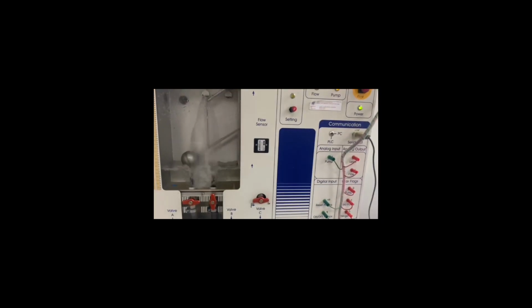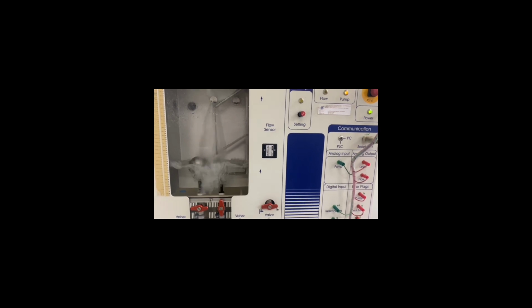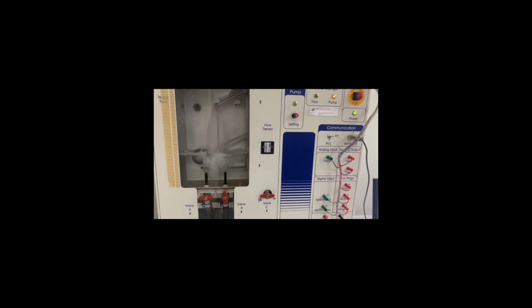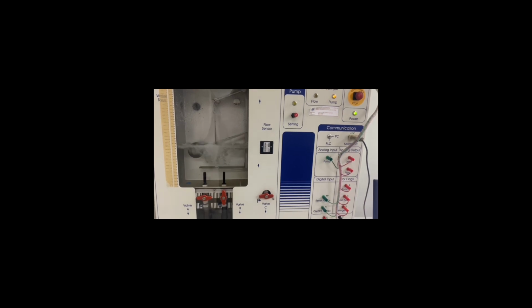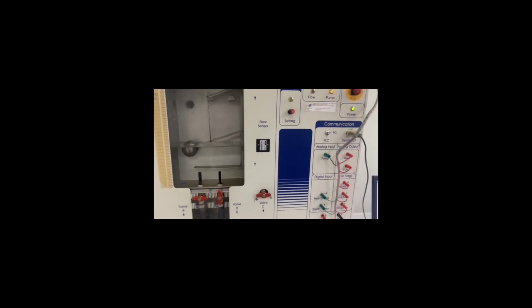I will continue the experiment video, and I will talk about the procedure for this experiment. The first step is to turn on the computer and run the Process Motion software. For the first task, at the screen, click online, click the level control or process button, and select the PID controller from the dialog box and enter the input for set point 120, KC 5, TI 100,000, TD 0, and MO 0. And click run and run the system until it reaches steady state.